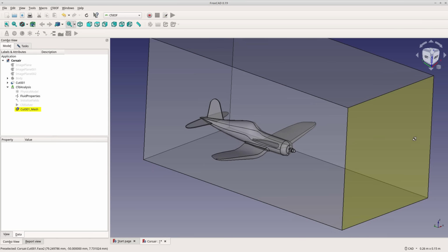Once we have our mesh, we're going to be ready to solve. Actually no, we'll have to add boundary layers. So I have to determine what is input and output. And I want to use kind of a unique direction on our flow to illustrate ways that you can tackle inlets and outlets to be a little bit more realistic.